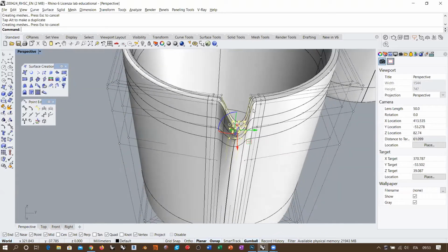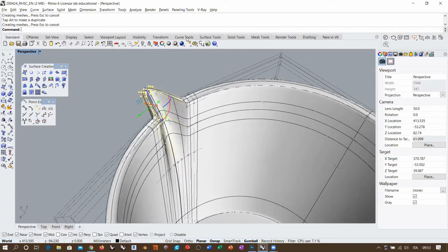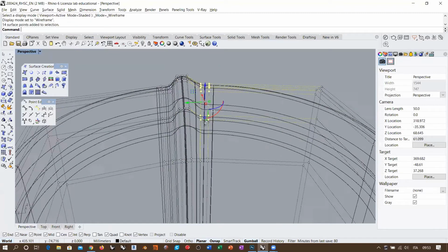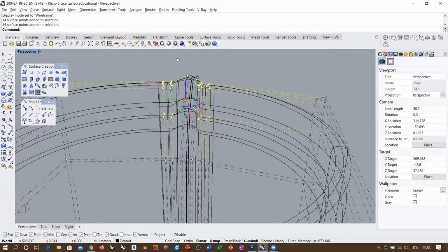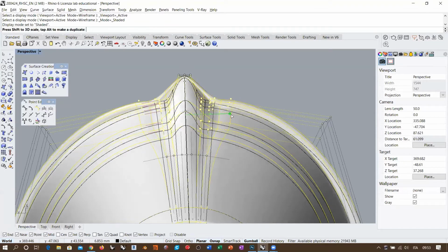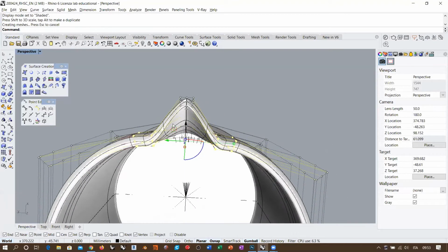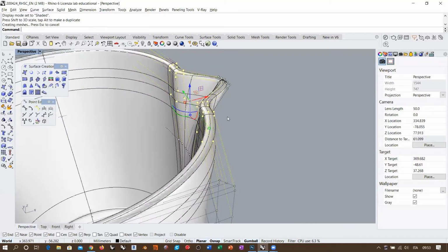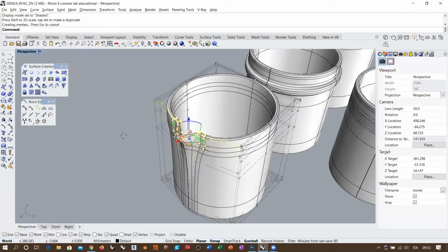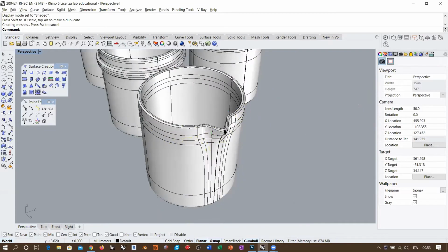And this is also still more evident if I work with these new control points here. If I work with them, I can do basically whatever I want. So if I select this set of control points and this set of control points here, I can, I don't know, move them apart in order to recover some uniform thickness here and do whatever I want, and still I'm not creating any kink line or any crease along the surface, okay?